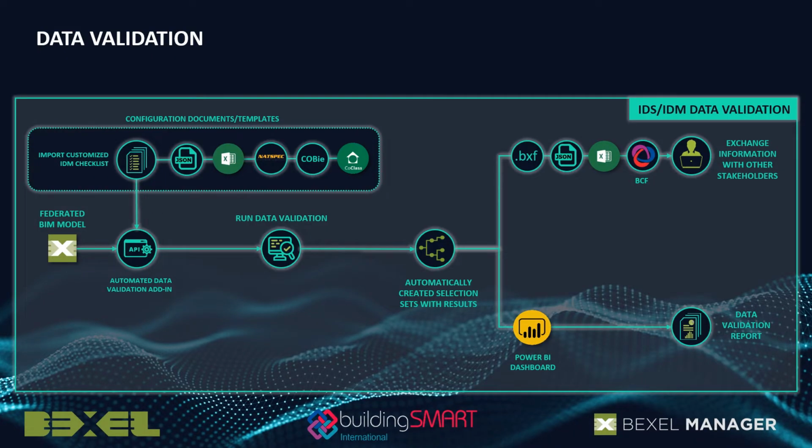After model elements are properly sorted into groups that allow the user to easily navigate and control the model, the next important step is data validation, or checking if the data in the model are corresponding to the set parameters or set rules in the BIM execution plan. This process could be executed manually, so the user can go through the sets of data and check if these data comply with the rules specified in the early project phases. But this will also be an extremely labor intensive task with a lot of repetitive work.